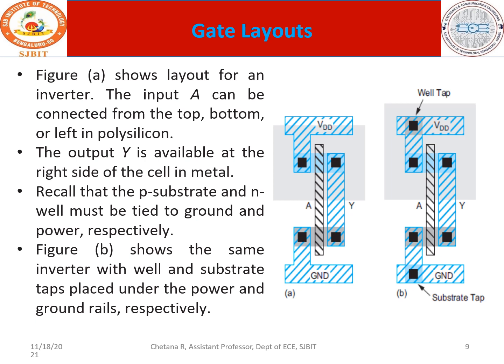So what exactly do you mean by well and substrate taps? The well is coming inside and there is a tapping taken over here. Similarly in the substrate. So you have a strong connection, strong contact between the well, which is normally connected to VDD, and the substrate, which is connected to the source, and it is grounded.